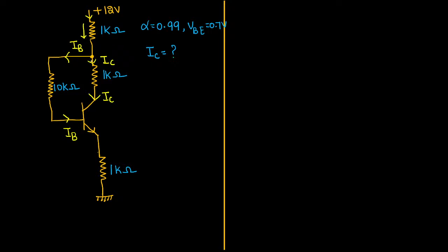If you apply KCL, Kirchhoff's current law, I can easily say that the value of emitter current IE equals collector current IC plus base current IB. Yes, sir. This conclusion is over. This is the one conclusion I got. Now, how should I explore all the values?